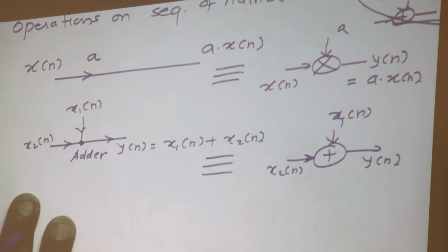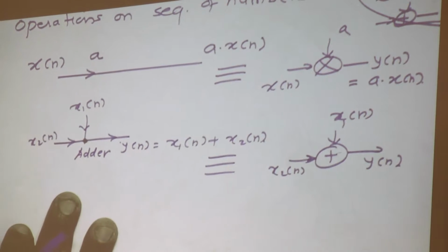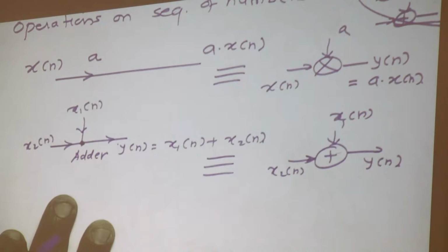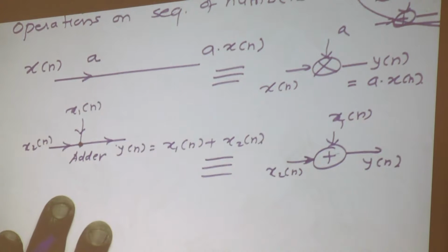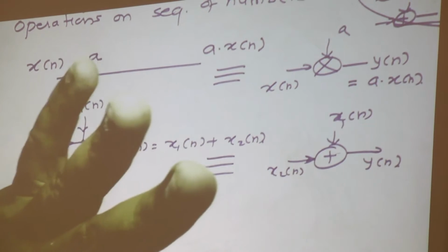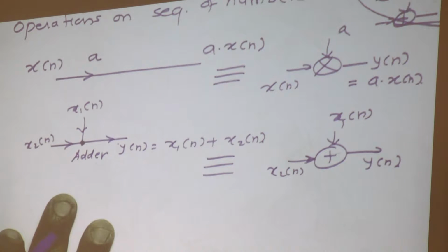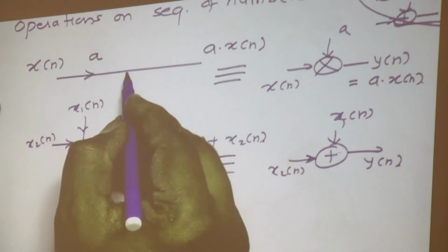These are digital circuits. An adder is a digital circuit, an 8-bit full adder or 8-bit carry look ahead adder, or any other adder, maybe a bit serial adder. Whatever adder it is, it is actually an 8-bit adder. The inside structure of that adder could be an 8-bit full adder with the least significant bit using a half adder, and all others will be 1-bit full adders. So, it makes an 8-bit full adder or 16-bit full adder, depends on what is this arrow.